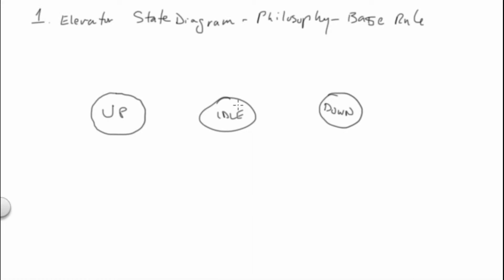So basically, if you can see these 3 basic states and then start building on them, you can build the sequence for the elevator state diagrams. So you can build all the parts and pieces based on these 3. So you would say, I'm going up and I'm at this point, but I'm going up and I just hit the limit switch, and I'm going to stop at that floor. There's a request to stop at that floor, and I hit the limit switch just prior to that floor.